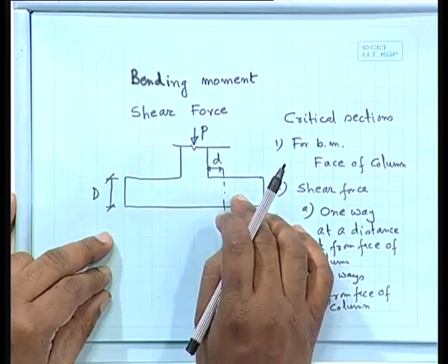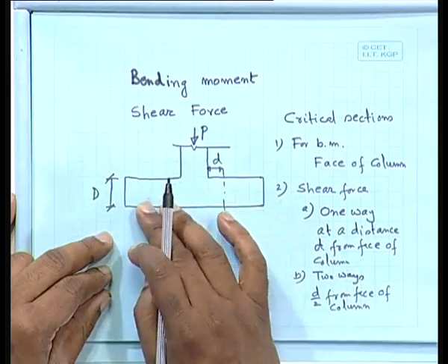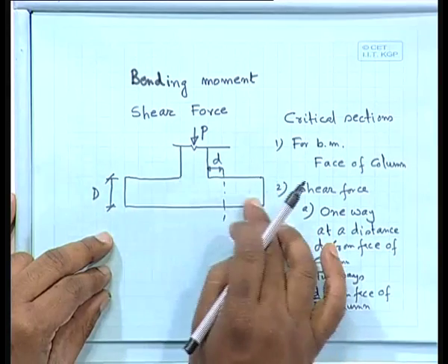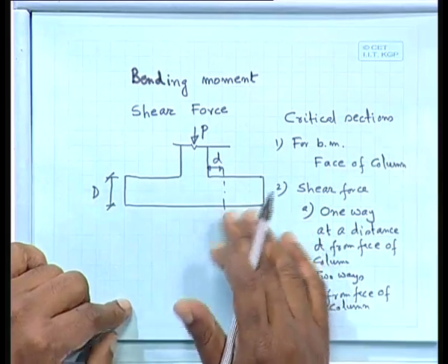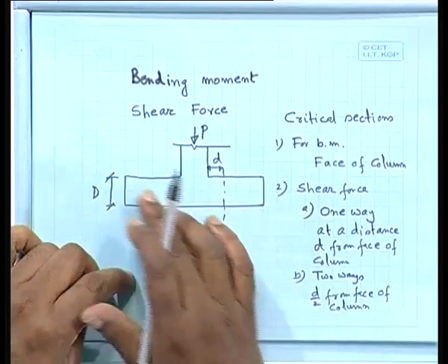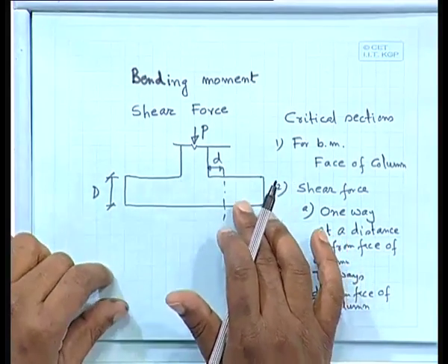You are not providing any shear reinforcement, no stirrup, only you are providing, say, your slab. So, here the critical stress tau c should be less than 0.35, that you should consider, because if it is more, then you have to provide shear reinforcement, but generally in this type of footing we do not provide any shear reinforcement, there is no provision for that.